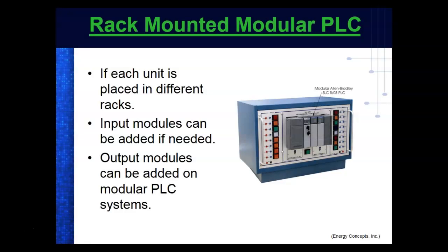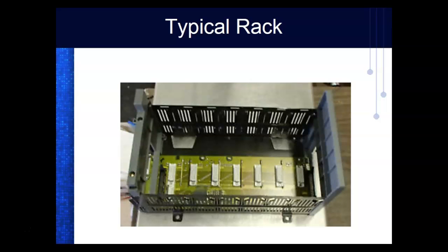This is a modular PLC. This is the old way, and they're still available, guys. You can still buy a fully modular PLC. A modular PLC, and this is a trainer, has a rack. So this is the rack, and then it has what we call a backplane. This carries all the power and addressing information from the CPU module to all the other modules. So this would be what we call a 7-slot rack.